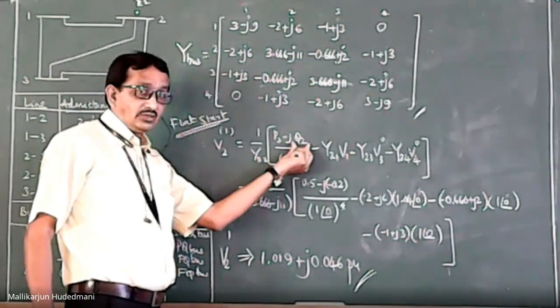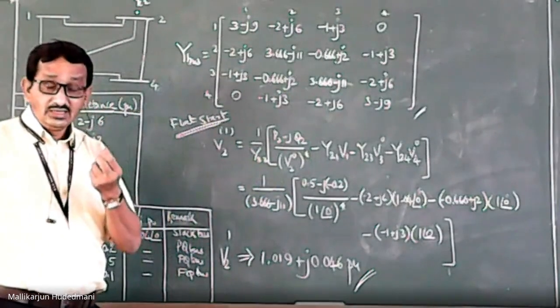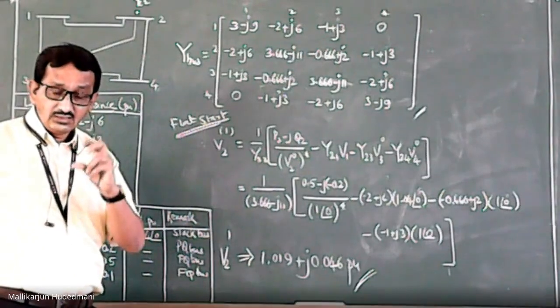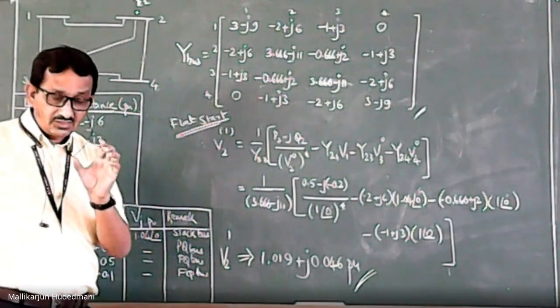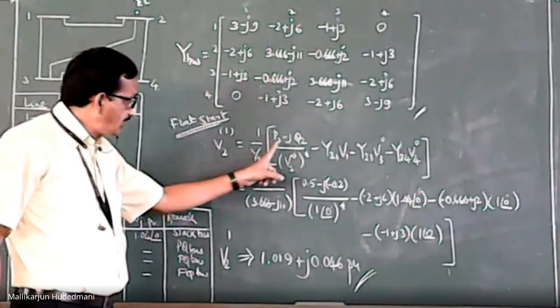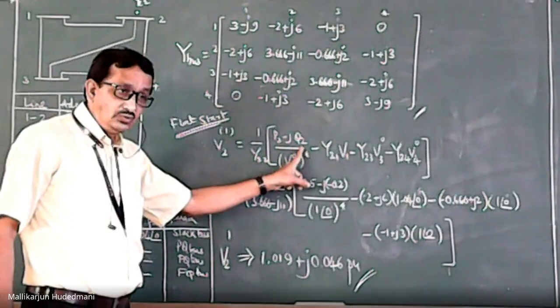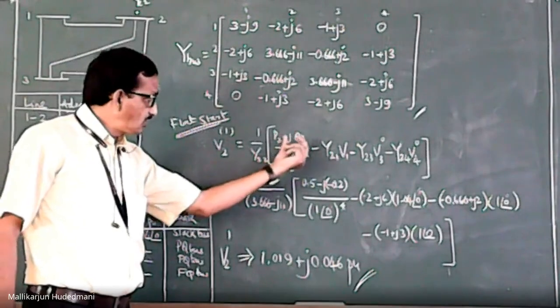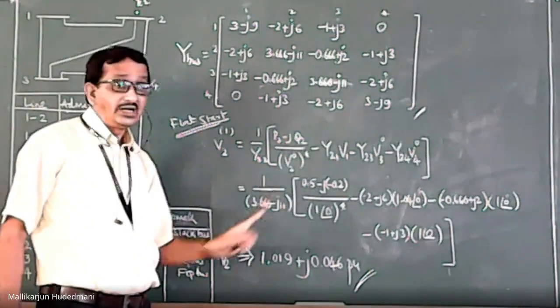Similarly, what is the reactive power and active power situation at that bus? It is the net generation at that bus minus the demand at that bus. For the active power value, that difference is P2 for bus number 2. Similarly, reactive power generation Qg2 minus Qd2 demand, that differential value is called Q2. So this way, these values must be identified.